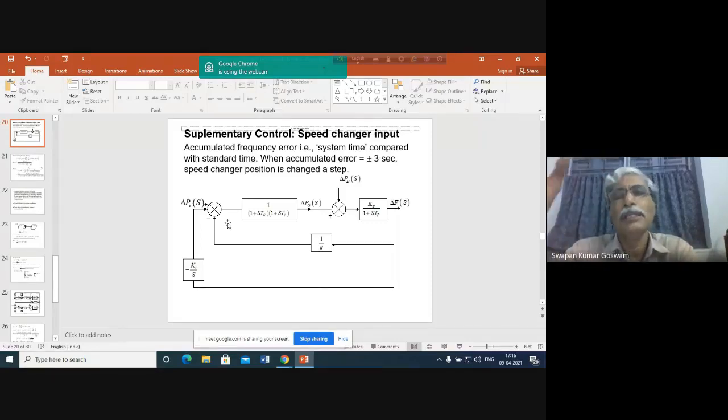If you have 100 megawatt declared capacity, you should maintain at least 62.5 megawatt. This much of capacity must be utilized to supply power. Unless you supply this, you will not get the full revenue that you should earn by selling power to the power system.